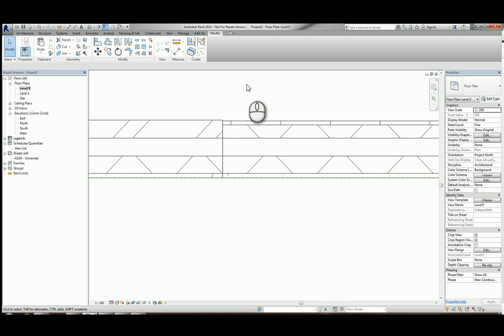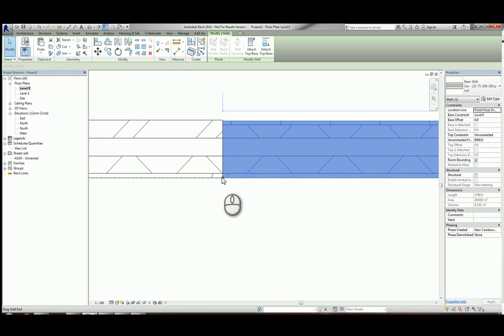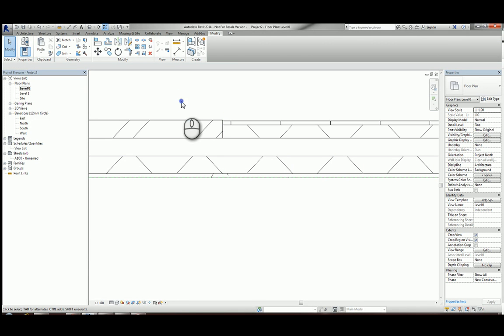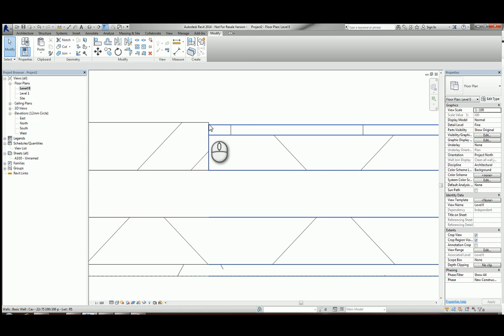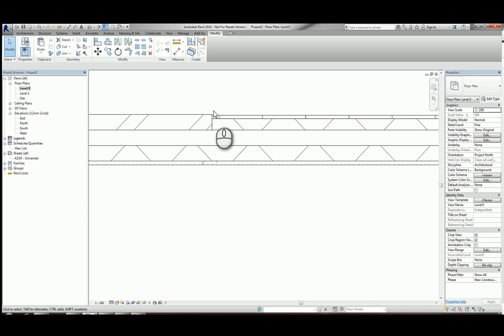In fact, if I just drag that wall just a touch over there like that, so they join up, there we go. It looks nice. It's like a nice detail now. We've even got my render inset from the edge of my brickwork to stop weathering to my render. Very good. You think I've done this detail before? So you can see how that's going to work, and that looks quite nice. However, it will cause problems in other ways.